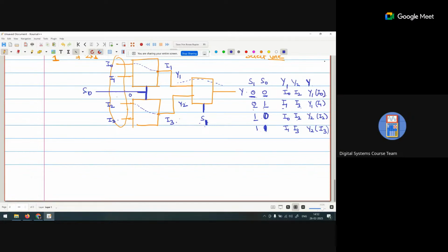So that means this select line sequence is correct. When we are designing a basic single mux, our sequence of the select lines is from MSB to LSB, moving from right to left. This is the MSB and this is the LSB.